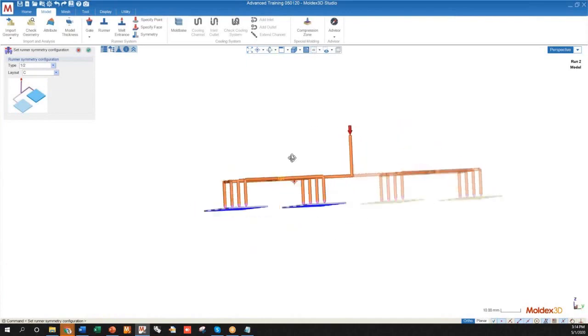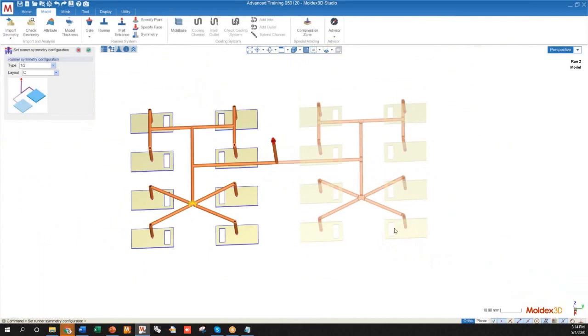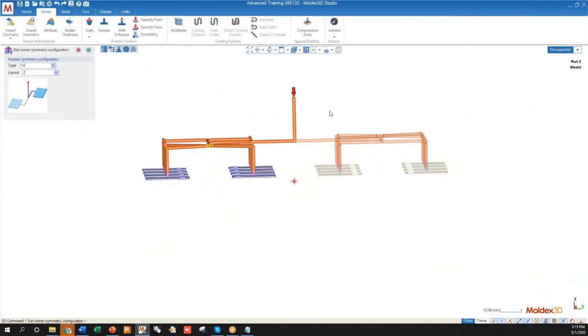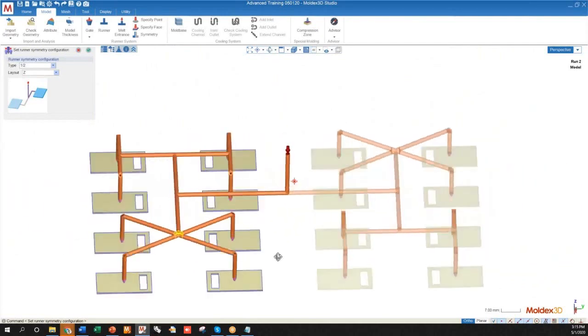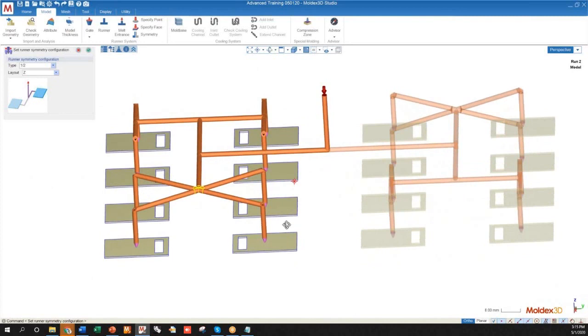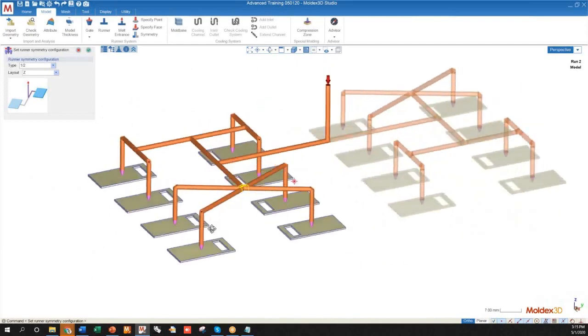you'll see that that will just be copied over. And this section wouldn't be modeled with physical elements. We would actually be able to consider them virtually. Essentially what we're doing with this symmetry function is we're saying that whatever happens on this side of the mold is also going to happen on this side of the mold. It's just the pressure required to push the material that far into both sections is going to be doubled. So we're going to take whatever pressure is required to fill out this system, double it, and that would be the exact molding scenario as doing a 16 cavity mold instead.